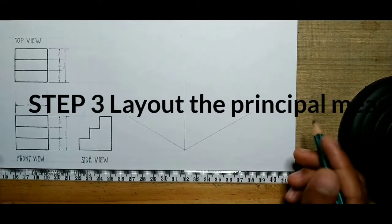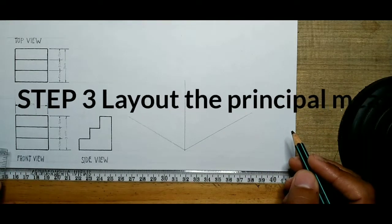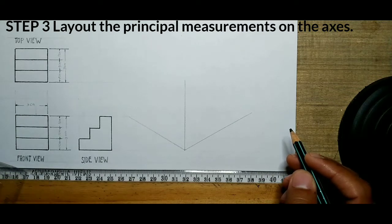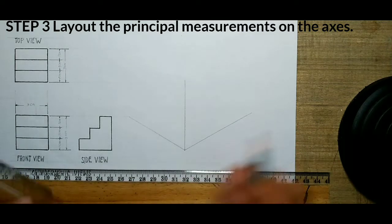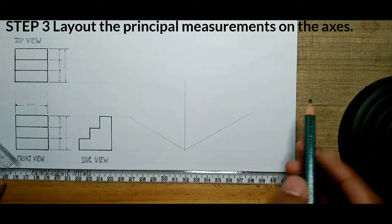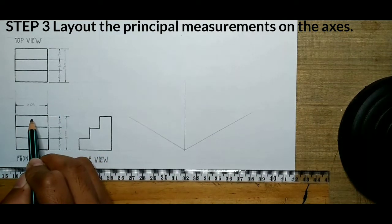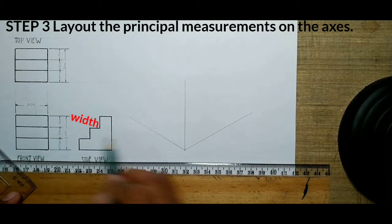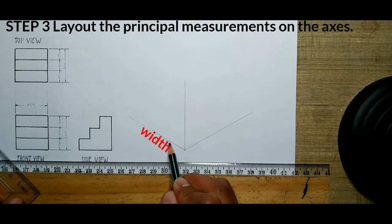Step number 3. You lay out the principal measurements on the axis. Get these measurements from the orthographic views. The width of the object will be measured to the left cross axis.